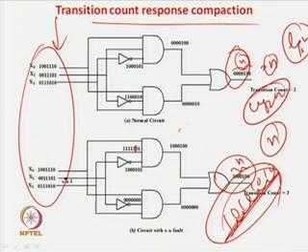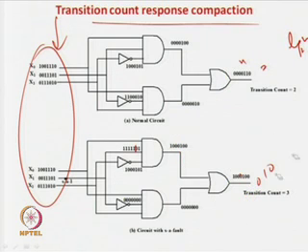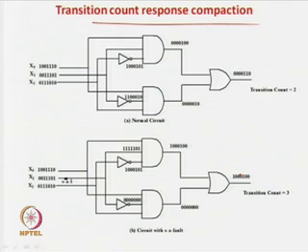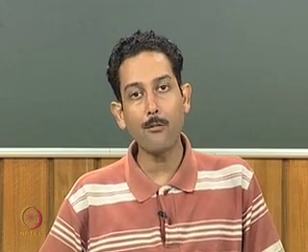So if you store the outputs flat, you require n bits to store it, if the output is n bit length. But if you are using the ones count or transition count, you require log 2n. So that is the factor we have saved in these two compression schemes we have seen. But again, sometimes there is an aliasing effect and all those things. Also, you have to understand that for one such output you have saved from n to log n, but if there are a large number of outputs, then for every output you will be saving from n to log of n.